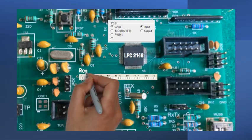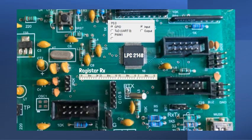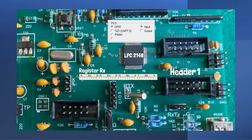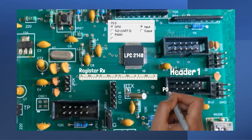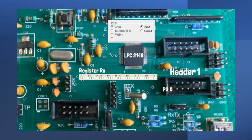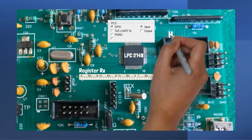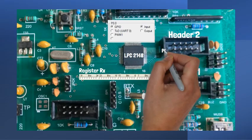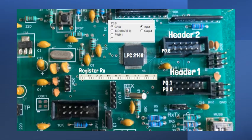ARM7 registers are 32 bits in size. ARM7 can read or write 32 I/O pins in one cycle. CPU register bits are directly mapped to individual I/O pins. I/O pins are terminated in groups of 8 on a header. If we connect any peripheral to header 1, we use bit 0 to bit 7 of the 32-bit register. If we connect any peripheral to header 2, then we use bit 8 to bit 15. If we want to use header 3, then this header's bits are mapped to bit 16 to bit 23 of the registers used.